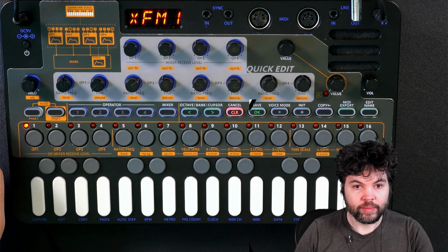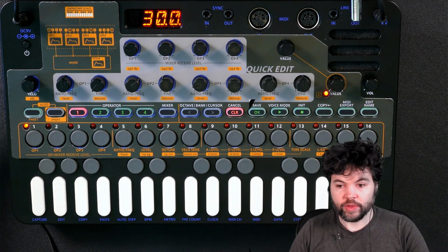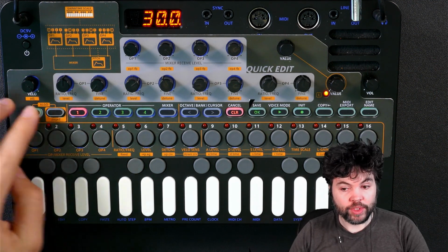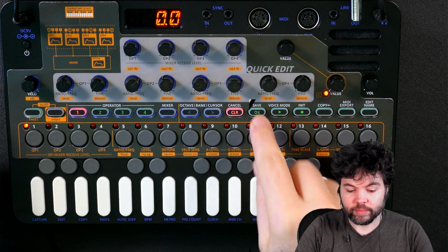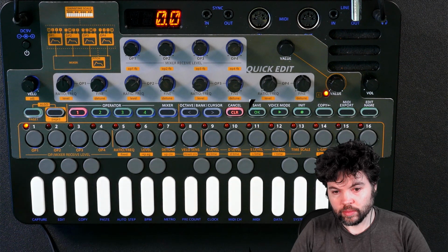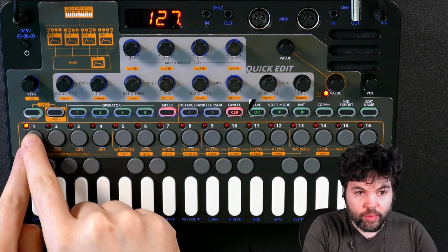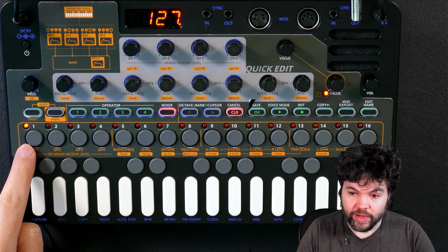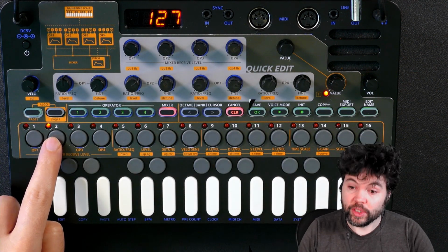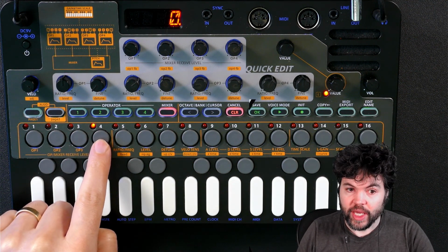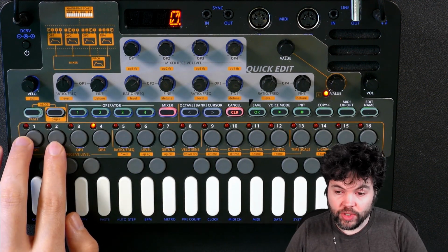As before, edit mode, let's open the first patch, let's initialize the patch. So this is just an init patch, but now what we're going to do is select an algorithm. So if I remember correctly, we wanted algorithm 4. Okay, so let's have a look at how it's set up at the moment. You can see operator 1, the mixer level is 127 because it's a carrier. Operator 2, the mixer level is 127 because it was supposed to be a carrier. Operator 3 and operator 4 do not output to the mixer. So what we have defined here are the two carriers.